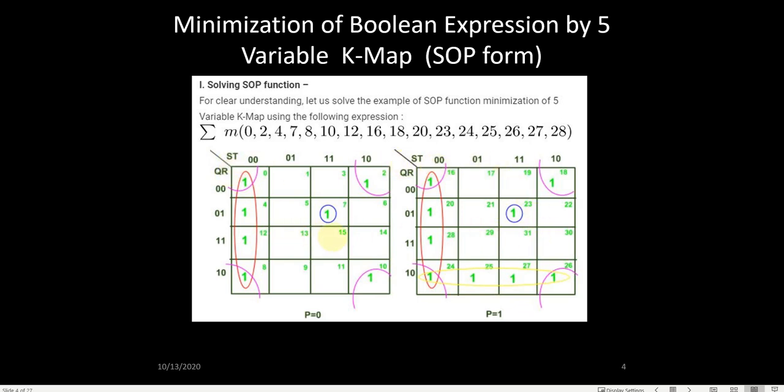With the MSB taken out, Q R S T we had made into different K maps. First we make the K maps individually, right? So these are the 4 K maps. Now after having made them individually, we have to see whether a group is available here also, right? That means it is not dependent on P. So this long one is actually S dash T, right?